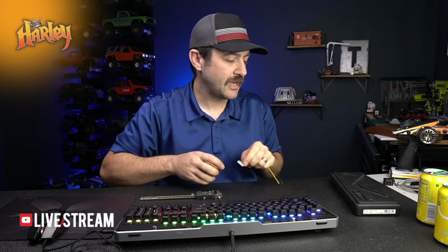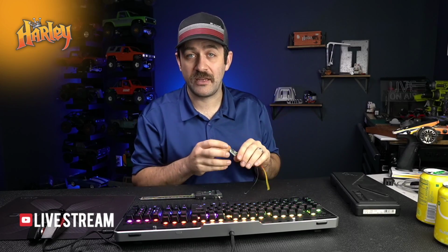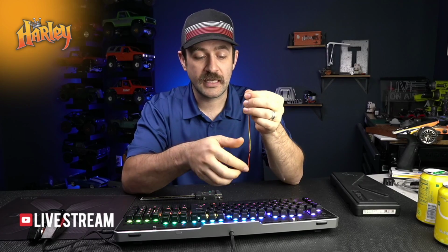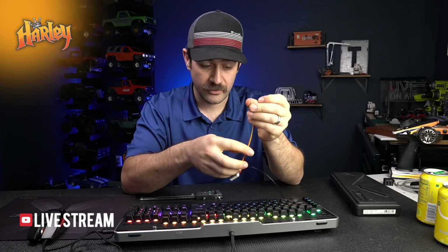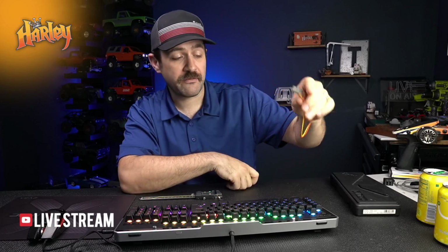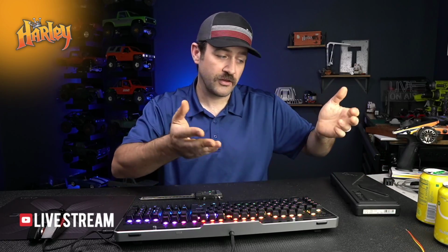Pretty handy to have. And it's actually handy to have in your vehicle. You just wire the red and yellow to one side, you run that to your positive and the black to your negative. And then you can tell where your battery voltage is at on your vehicle. Again, it's nice to have. You can tell where your car's at all the time when you're on the trail. Super simple.